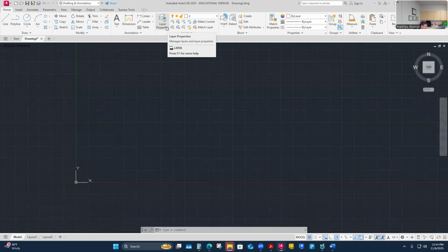And in your drawing class, you learn the reason we need different line types is that's how, in a black and white print, I'm able to determine different line types. Hidden lines are a really consistently dashed line. Center lines are long and short dashes, a consistent pattern too, and phantom lines. So I'm able to change the line types using the layers essentially. I know it's called layers, but you can almost consider it line types, which is maybe a little more helpful. It's like programming a bunch of different line types that I'm going to draw with. And then I color code those so they pop and stand out a little differently. And that's all that is about.